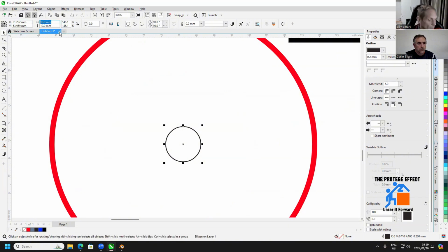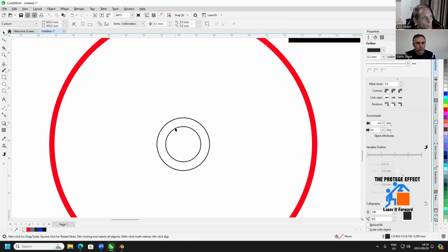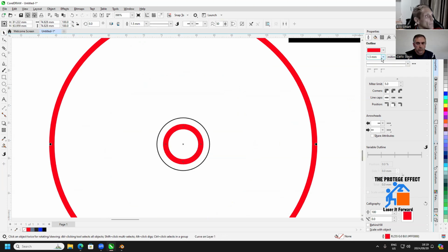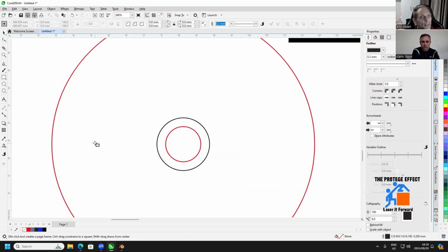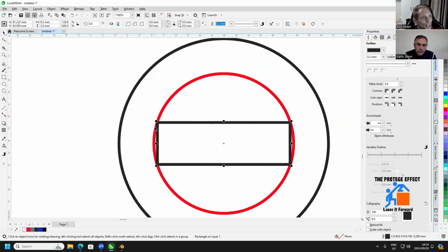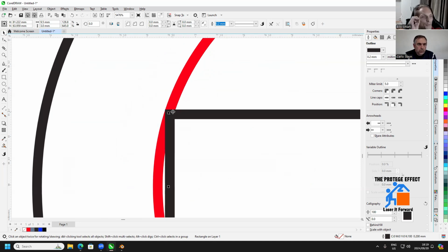Let's make another one quick. I trust my system so much that I know I'm not going to redo work if I do that. I'm just going to hairline it so that it's quite a bit thinner. We said that other little slot where my wheels are going to fit on is 3 mil thick, and I said it's 9.5 mil wide, correct? Yes. Look what happens if I put this in the center of my little circle and I zoom right in for you. It's perfect.